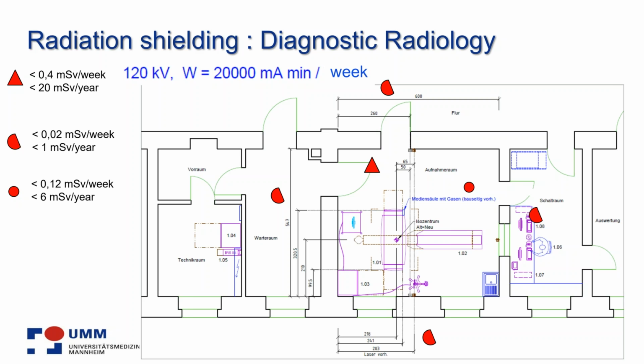And you see the operating area for the CT scanner on the right hand side, and you see there is a window as well. This green lined area is a window. So someone who is sitting and operates the machine has to be shielded in that manner. The place where he sits is a public place, and the limit value for the public place is 1 millisievert per year. So that means this person who sits in front of this window and operates the machine has no further exposure than if he were in the public during this time. Yeah, next one.